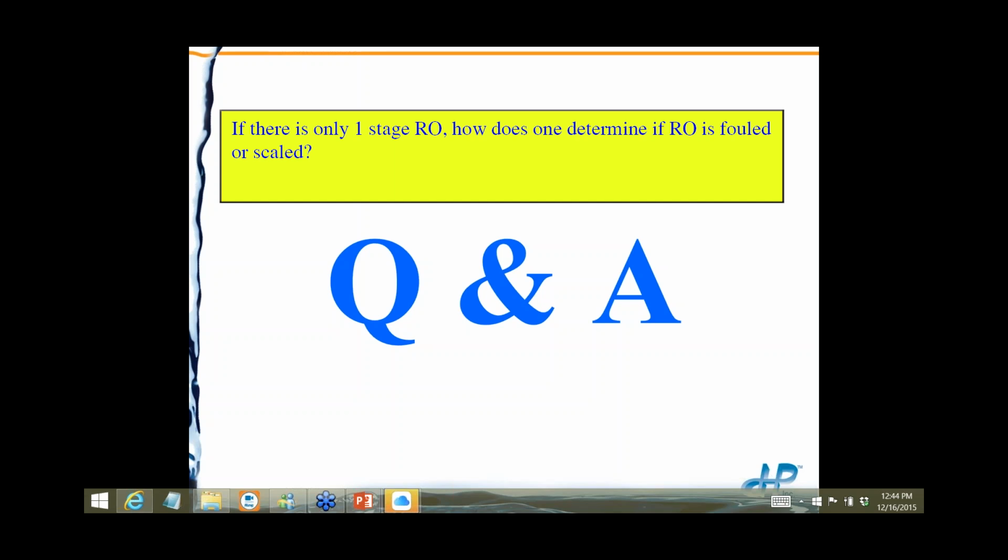As long as you know that your scale inhibitor is being injected and there isn't a scale inhibitor problem, such as your scale inhibitor has been biodegraded, so in a day tank, if you pump it full strength, then you'll never see that problem. But if you dilute scale inhibitor, then bacteria can grow and consume it.